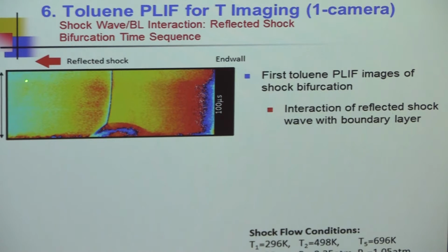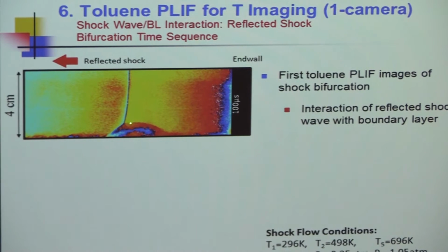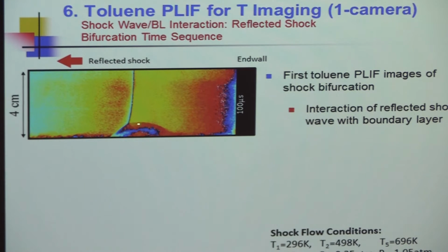And here's a distance of only 4 centimeters. So we're looking at a distance here of maybe 3/4 of a centimeter. So there's a boundary layer, which we're able to see. There's a shock wave which is now curved because it has to have this triple shock structure. And this should be a uniform region. You see the boundary now of this, this is called the jet here. So anyway, we're able to examine the structure of this fluid mechanics disturbance.